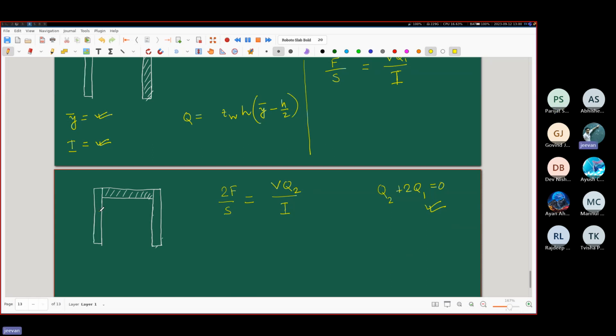The material itself. The actual wooden material is providing the support. So, in order to keep this thing intact, there is actually a shear force which is equal in magnitude to the shear force being supported by the nails. Actually, it is the other way around. If the material had been one piece, then the wooden material itself would have provided the required shear force. But there is no fiber connecting the wooden fibers here. The absence of those natural fibers which would be supporting it, that responsibility is being taken up by the nails. That is why this F is coming for the nails.